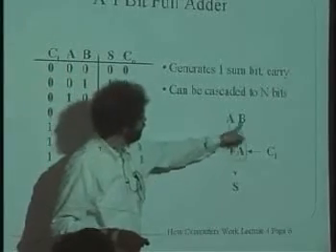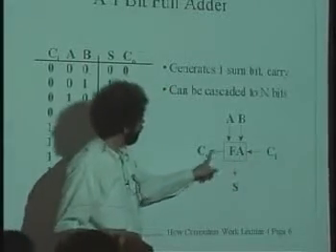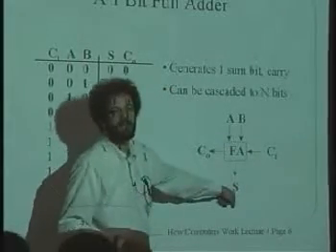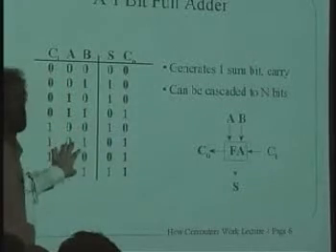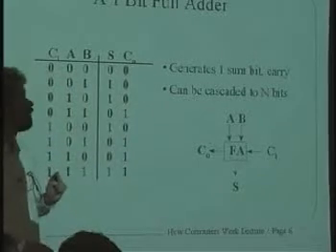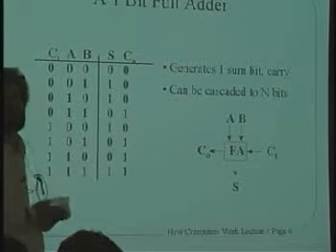A sub i comes in here, B sub i comes in here, carry in goes in here, carry out goes out here, and the sum bit pops out down at the bottom. We can describe this with a map exactly like what I just showed you over there, except luckily now we have far fewer than 2 to the 70 bits.